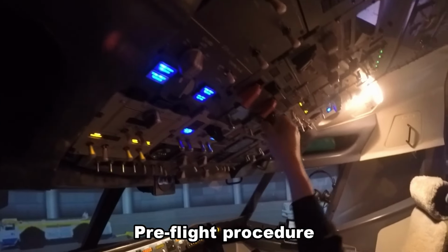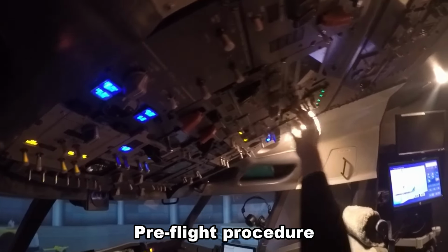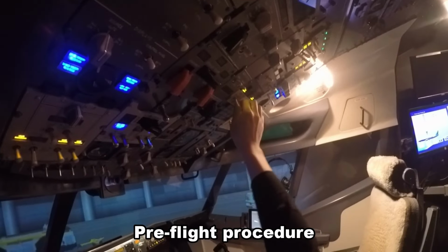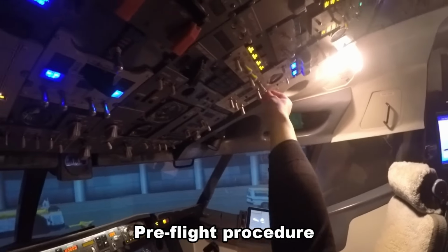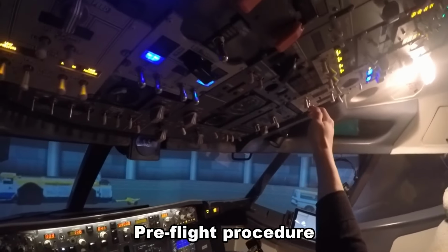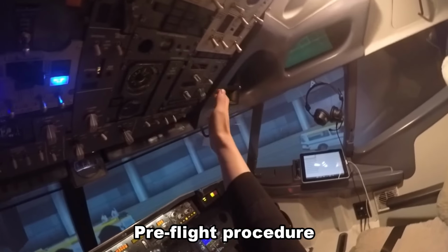Fasten seatbelt signs, the emergency exit lights are armed. Window heats are on, the probe heat should be off. Anti-ice off, hydraulic panel, we'll just set that. Recirc fans are on. Packs, we're currently set to auto. We'll have the isolation valve open, the engine and APU bleed valves are open.